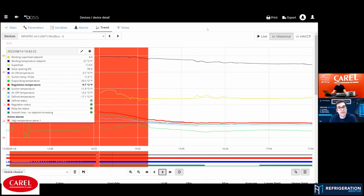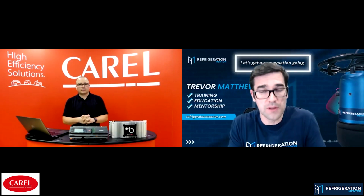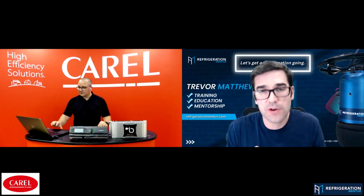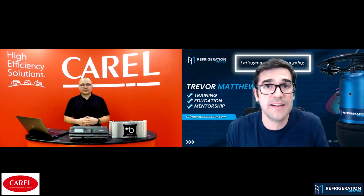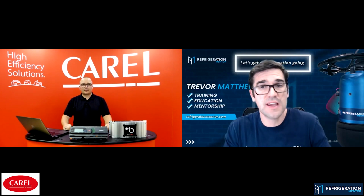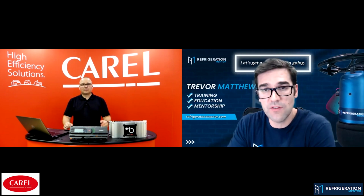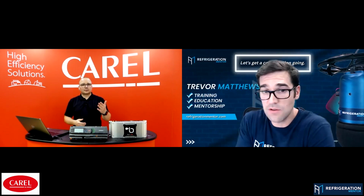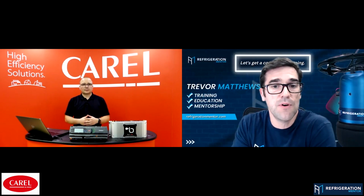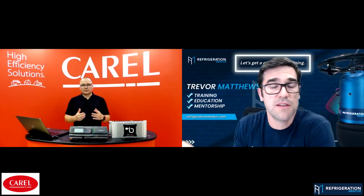Like I said earlier, get in and take a look at these graphs, get an understanding of what they do normally. And then when things like that start to happen remotely, because more people are going to be working remotely. It's happened. I did it 15 years ago. We could dial into stores then, and it's just getting more advanced. When you're working with your customers, you can see this, and you can start to tell stuff even before you get to a job site. Like right there, you could already know, okay, it's not refrigerant at that point. The airflow is good. The in and out is looking good, but the temperature keeps rising. What's going on?